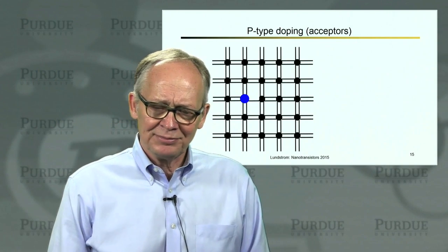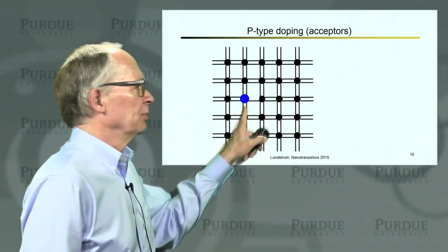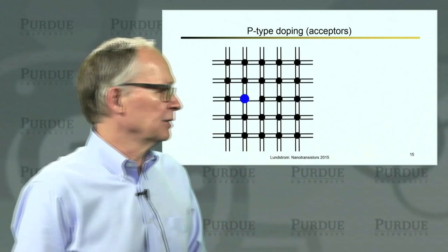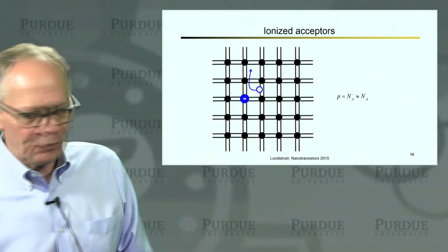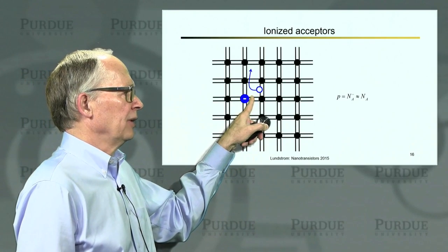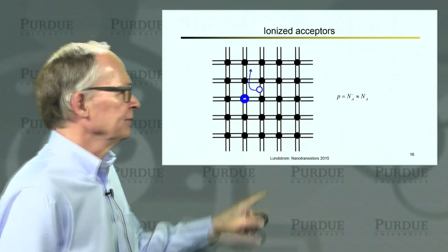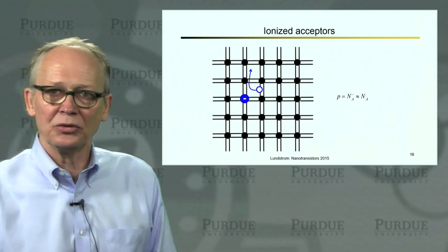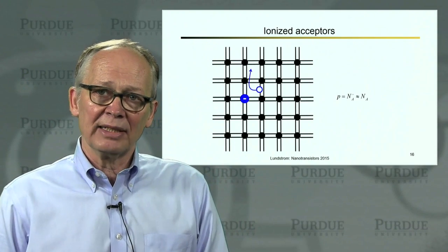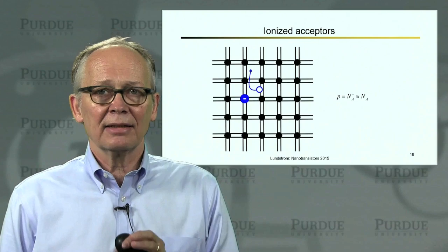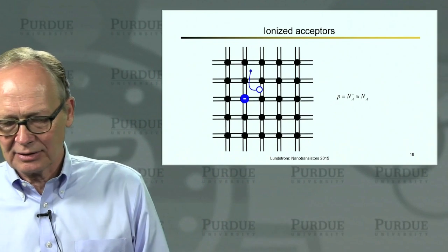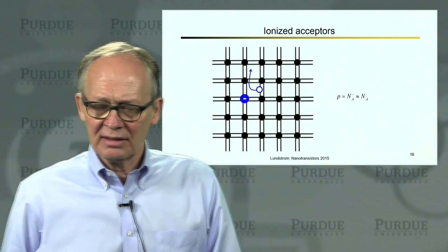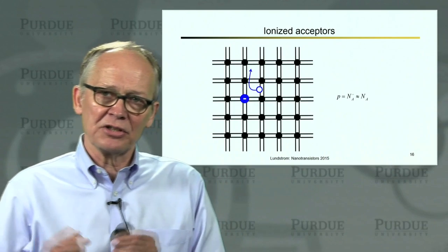Now we can do the same complementary thing with boron. If we put boron in the silicon lattice, we only have 3 valence electrons, so we're missing a bond. So we have a missing place there. Now, one of its neighbors can hop over and fill that up, and now I have a hole in one of its neighbors. And now one of its neighboring electron covalent bonds can hop in and fill that, and the hole moves. So if I put a column 3 element in, something very similar happens. It's just that I get a concentration of holes in the valence band, or positive charge carriers, equal to the concentration of the number of dopants that I put in. I'm assuming room temperature so that there's enough thermal energy to break this weak bond.